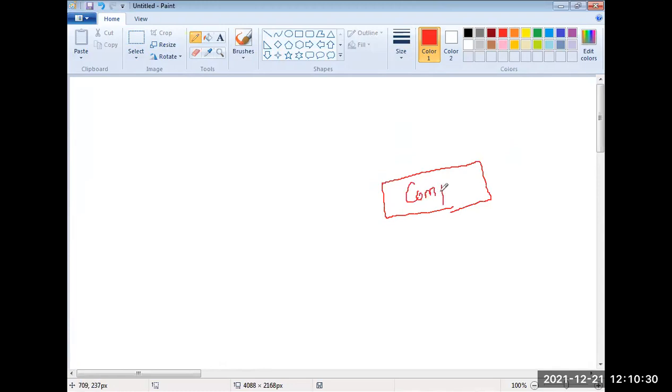This is my comparator. One value is given to the comparator from CCPR1H and CCPR1L, which hold 8 bits each of the total 16-bit comparison value. The value to be compared can be loaded in these registers. For example, it will hold 4B and 18.